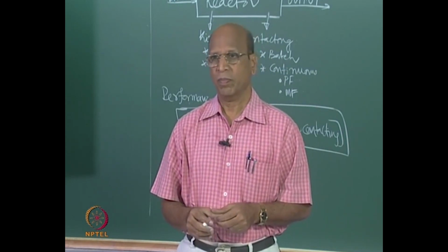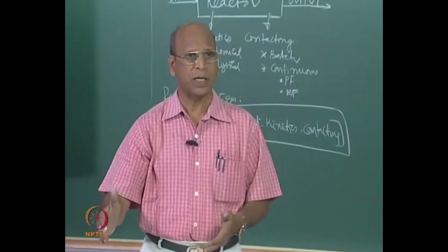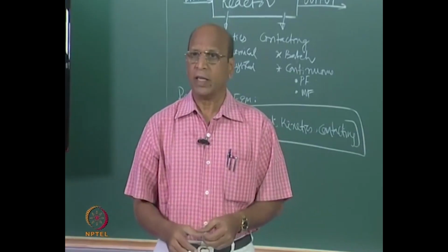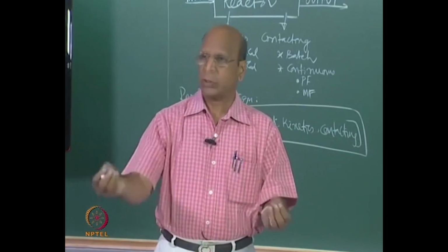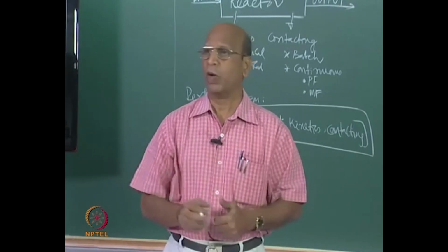If we do not want the concentration to fall down rapidly. Why don't you want concentration to fall rapidly? We want, because when concentration is falling rapidly, rate of reaction is high. When rate of reaction is high, time is very small and then I will get very small volume.